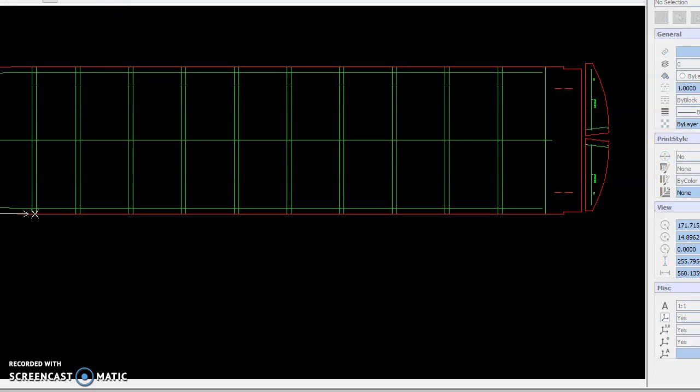I entered 384 for my distance to cover. I had to take 6 inches and add that for the rear pocket, so you end up with 390. That's correct. Cutting to the outside width of 96, add 2 inches for the system type, and your folds should end up with 98 finished, and unfinished is 101.2, which is correct.